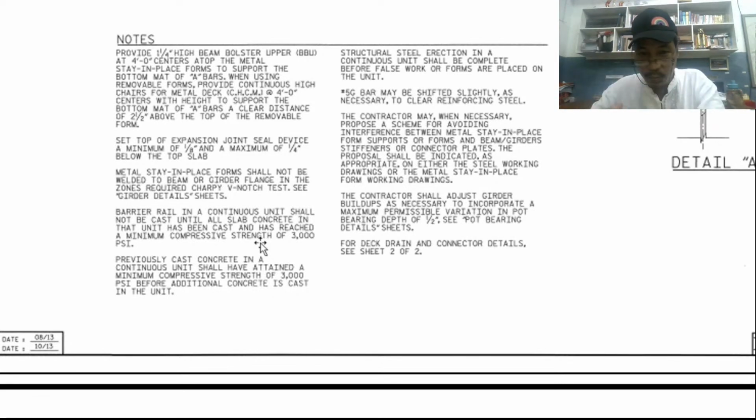And those test specimens, do you know why? Do you know what they are doing on those test specimens? After drying, those cylindrical specimens will be put inside the drum with water. Then, after several days, bring them to the laboratory for testing. And then they will give you the compressive strength number.